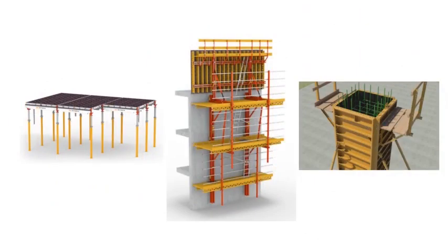The three main construction methods were Skydeck, RCS form, and EFCO. Skydeck and RCS form allow Absolute World towers to accurately implement different angles of slabs rotating on each layer, and the EFCO climbing elevator formwork system speeds up the turnaround time of the Absolute World tower's core.